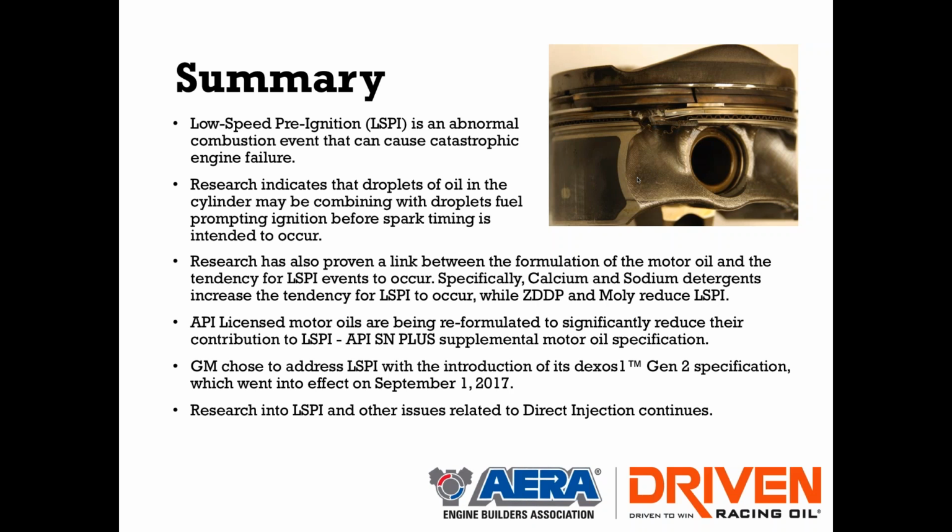Fortunately, the industry has made some big steps in the last few years, and now we have API SN Plus coming to the market. You'll see that rolling out the rest of this year. GM got a little ahead of the game and hopped out last fall with the Dexos 2 specification that is providing some LSPI protection in those formulations.